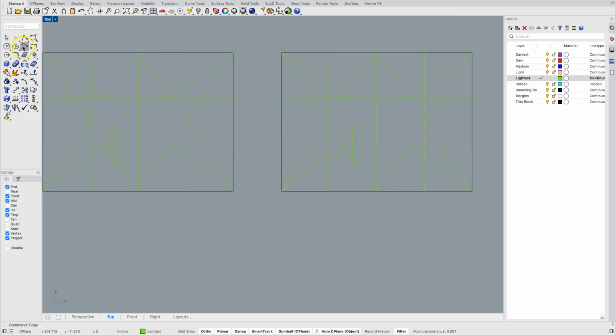Instead of choosing circle, I am going to do an arc with a center. So I'm going to do arc with center. So it wants the center of the arc. We know it's this line. What's its radius? We know it's up here to the upper corner of the square. So from midpoint of the base to the upper corner, one of the upper corners, we want to choose this one. And I can sweep down. I now have an arc.